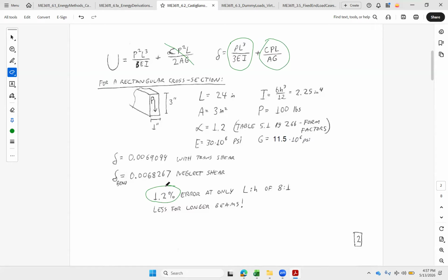We do want to keep V of X on our diagram because it's important for passing loads to other members, as well as creating the moment. The shear is often what builds our moment. But for a fairly short beam, it doesn't add up to very much of the total deflection. Did that help to illustrate the use versus not use for the transverse shear?